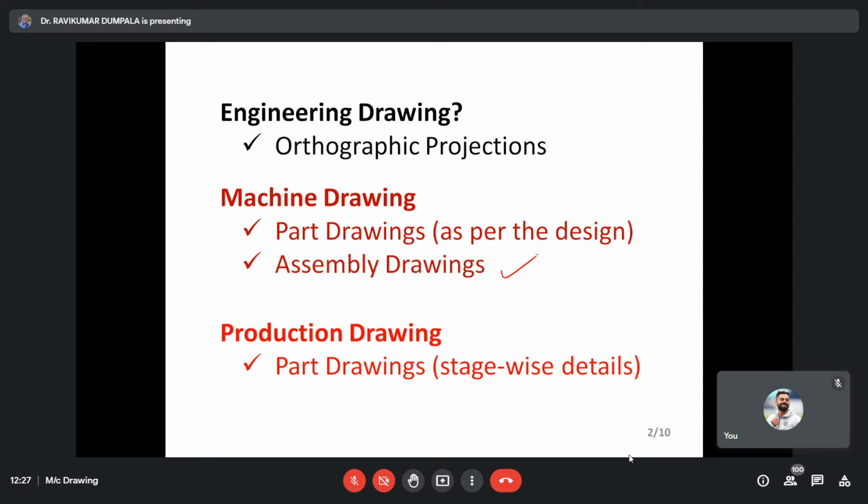So we don't go for finishing operations like grinding, reaming, or boring at the early stages, because those operations are required to get the close tolerances, which are generally required at the final stage. At the initial stages, you produce the components by forging, casting, and even rough turning. Going to the final stage, you use more precise machines and try to achieve close tolerances. You choose the process in such a way that you can achieve the close tolerances.